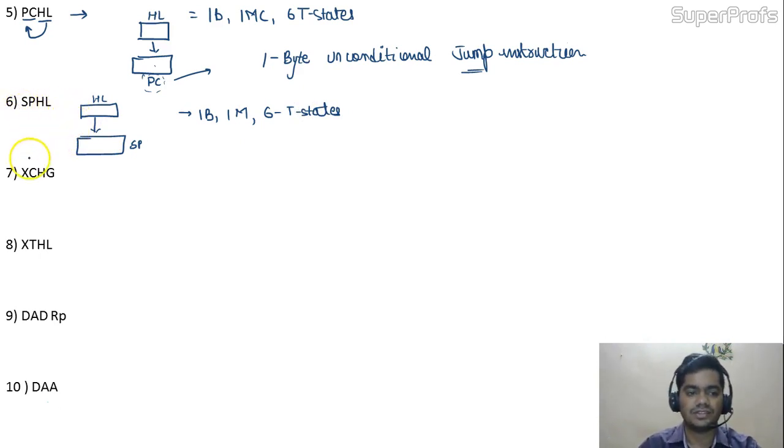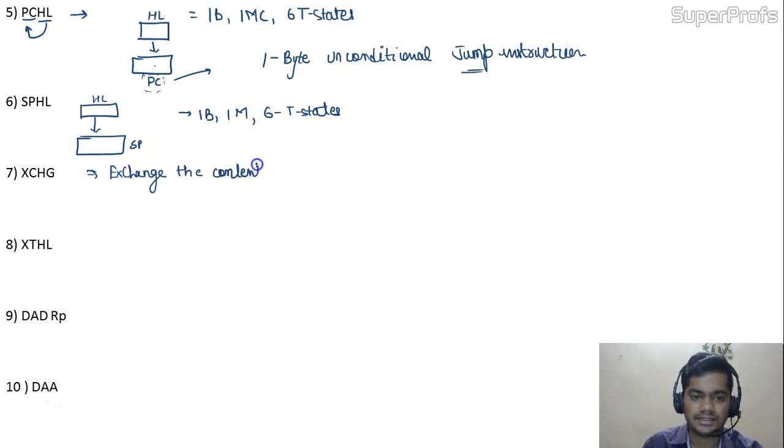Now we are going to see what is XCHG. So in this we are going to exchange the contents of DE and HL pair.